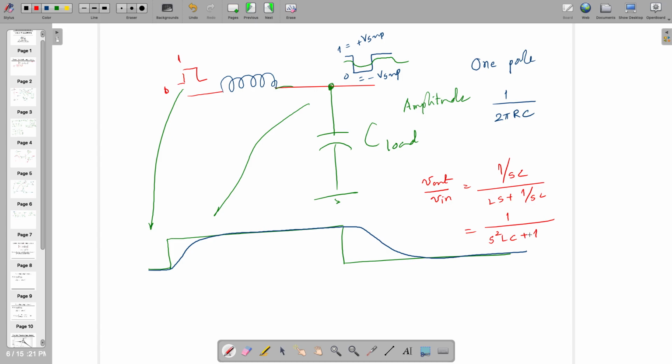Aishwarya and other people. This is what you must have learned in school, no? Okay, so tell me. This has to be on your fingertip. If you like I, you can write down I, but we write down J. Right? So root LC, right? Okay. If it is in hertz, then you need to add 2 pi, right? So this is omega P1 and P2, two poles, but these are complex and conjugate, right? So then what is going to happen?